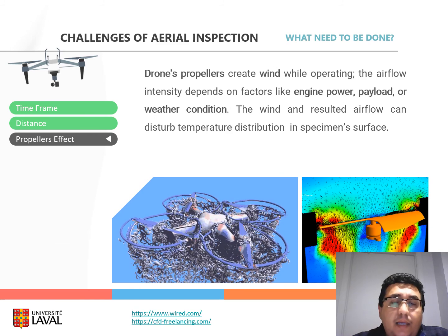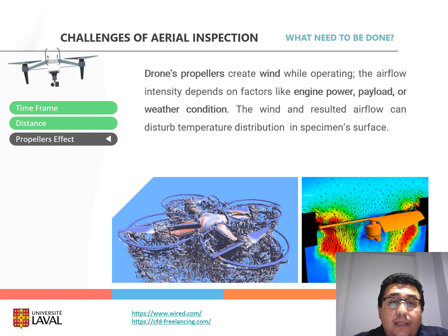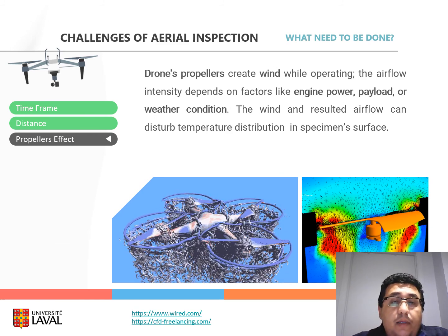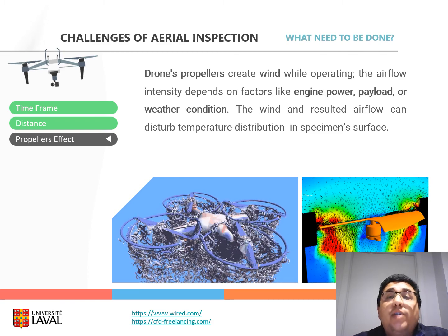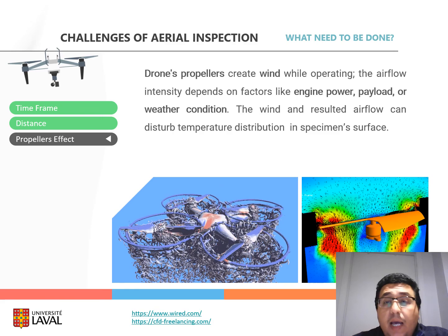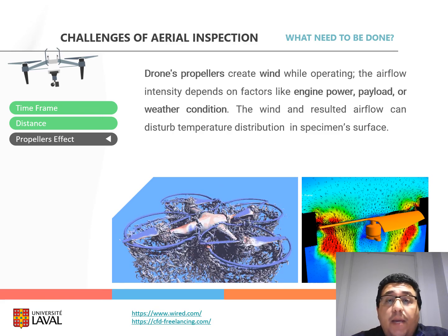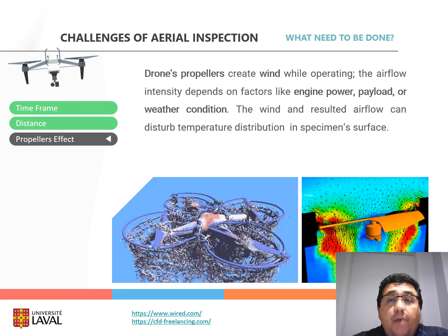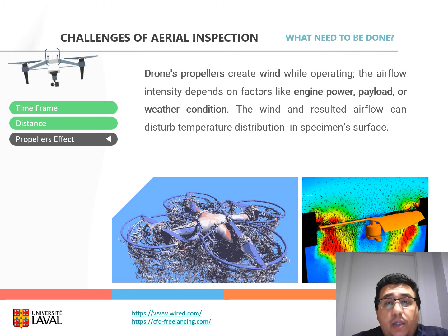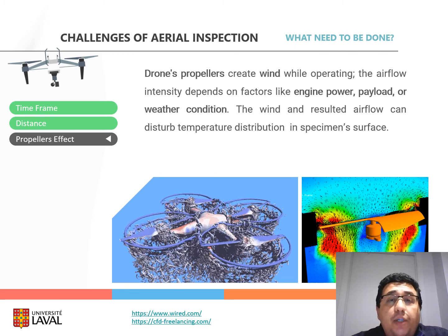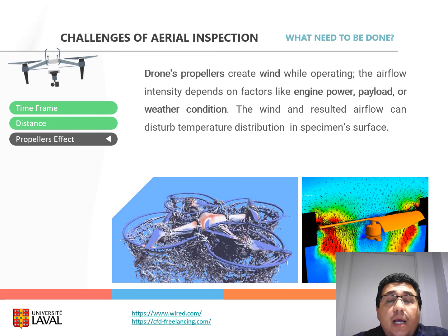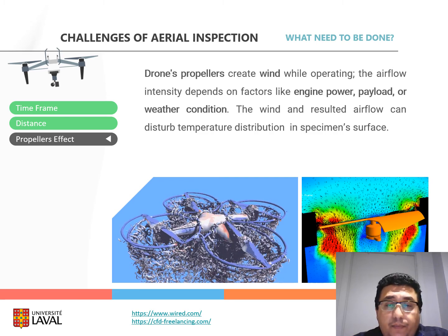The last item we want to discuss here is the effect of propellers. Drones' propellers create wind while operating. The airflow intensity depends on factors like engine power, payload, or weather conditions. The wind and resultant airflow can disturb the temperature distribution on the specimen surface.